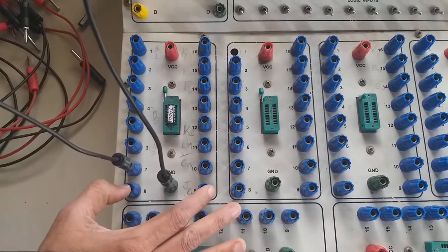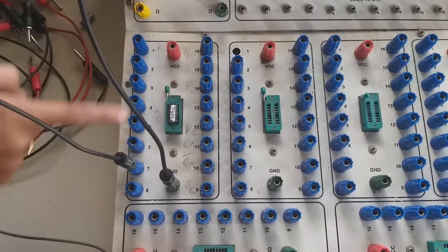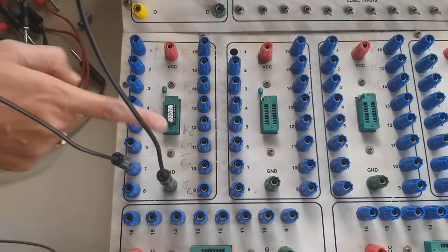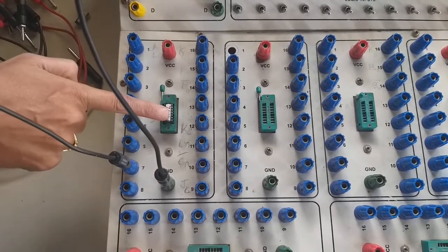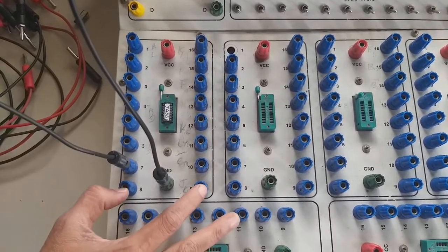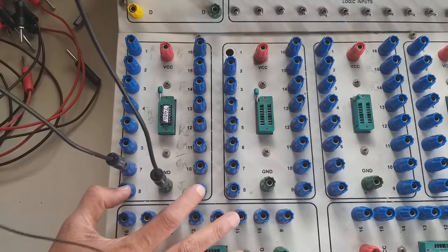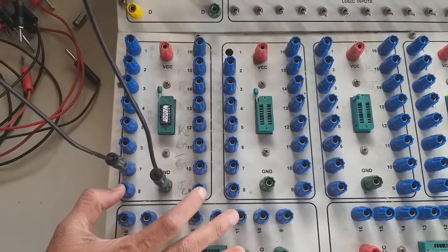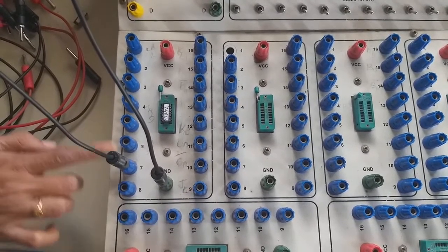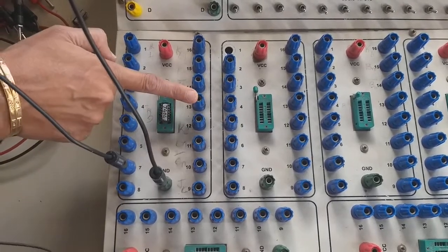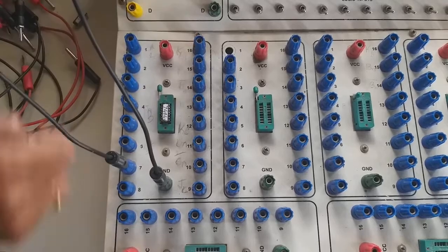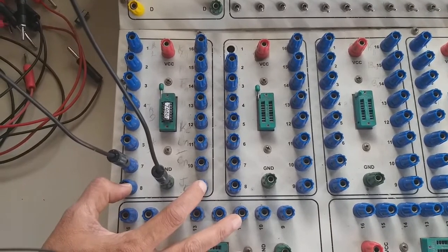Getting? Once again I'll repeat, this slot is of 16 pin IC. We are using the IC of 14 pin. So you leave the last two, 8 and the 9th pin empty. You're not supposed to connect it to these 2 points. So end it at 7. If this becomes 7, this becomes 8, 9, 10, 11, 12, 13 and 14. So you are supposed to neglect the last two.